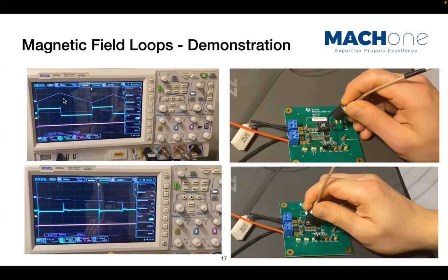And if I use the scope and do an integration calculation, then I can get the current waveform. So that's how I arrive at the current waveform. And of course, if I move the magnetic field loop close to a trace area or just a PCB ground area, then I pick up all these spiky waveforms, right? The same as we just saw in the simulation results.